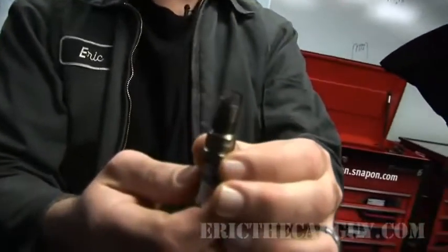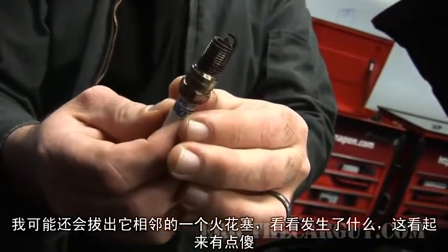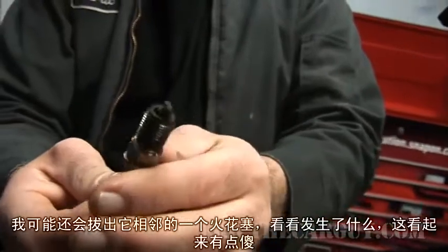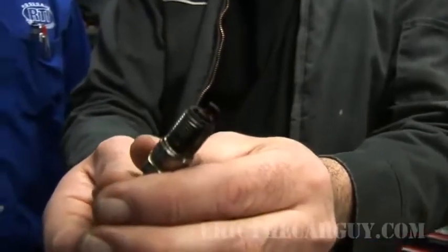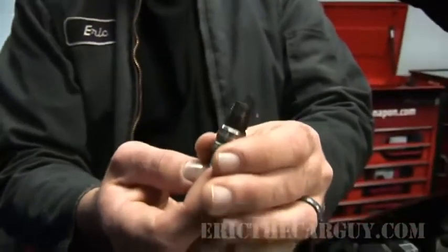What have we got here? What are we looking at? Look, again, I don't do spark plugs, this isn't my thing, so you're up now. It looks like a spark plug to me. It's not wet. That's right. I would expect something that was lean. I'd want to pull the one next to it to get a look and see what was going on. But it looks a little sooty. I would expect something that was lean to look a little bit cleaner, if I'm honest. Right, I'm not really seeing that.